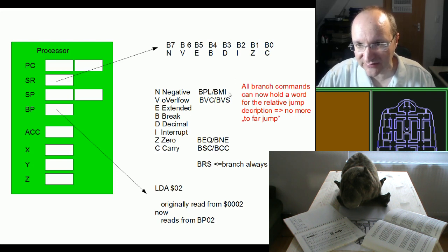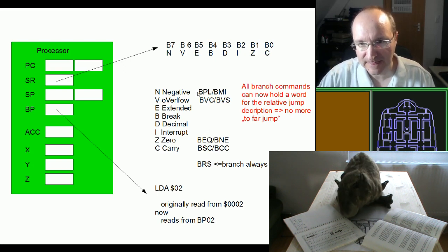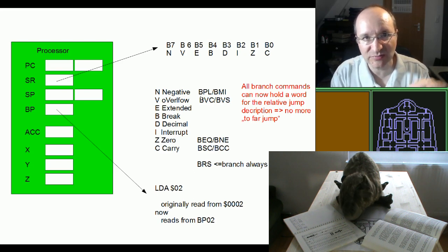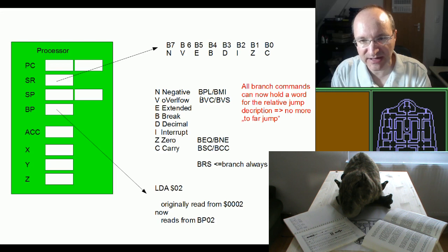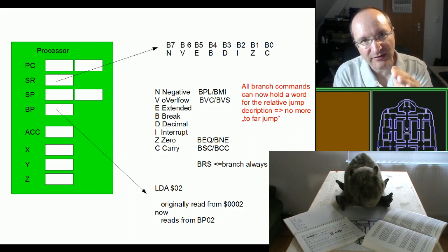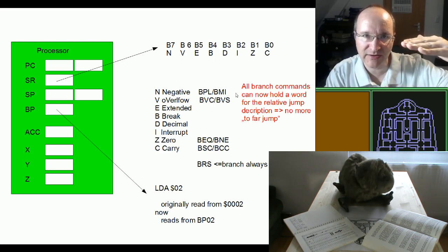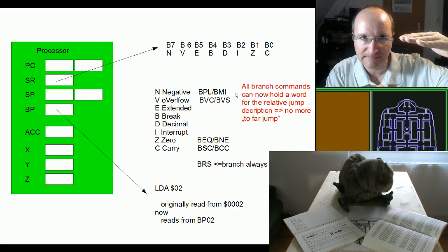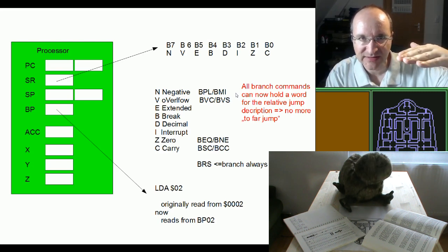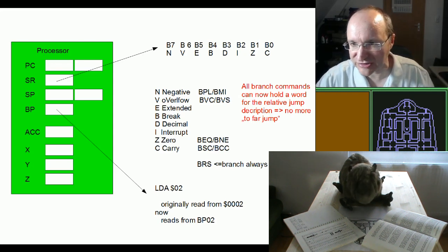And then also interesting, for all these jumps there is a second version. It makes no difference for you in programming, it's exactly the same naming. The assembler will decide which one to choose, because there is one that behaves as before, which can only jump in a small area, because you only have here one additional parameter in an 8-bit parameter, so you only can jump in an area of 256, so about 128 in one direction and 128 in the other direction.